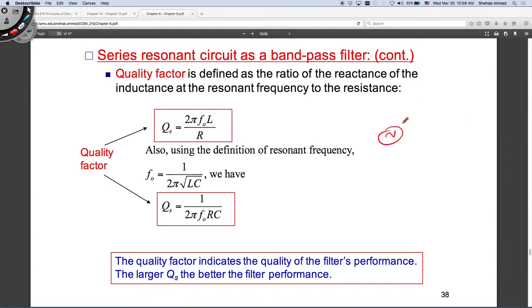the equivalent circuit we were dealing with was a source, right, at a specific frequency, and we had an R, L, and a C circuit, right, in series. And the objective was, at resonance, we wanted to maximize V output, right? So this was a certain resistance. If I think of it from a filter's perspective, I would like to make this one single frequency pass through with a high magnitude, right? That's what I would like to do.